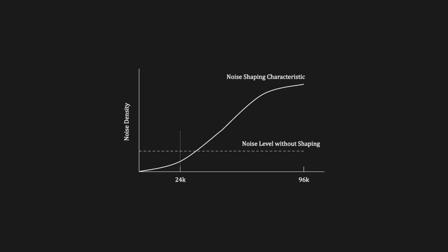Noise shaping, also called spectral shaping, goes a step further by controlling where that noise appears in the frequency spectrum. It changes the frequency response of the quantization error without affecting the audio signal itself. This technique is commonly used in both AD and DA converters, often through sigma-delta modulation. Normally, quantization errors produce white noise, spread evenly across frequencies, but by designing the error feedback system carefully, the noise can be redirected toward less audible frequencies.